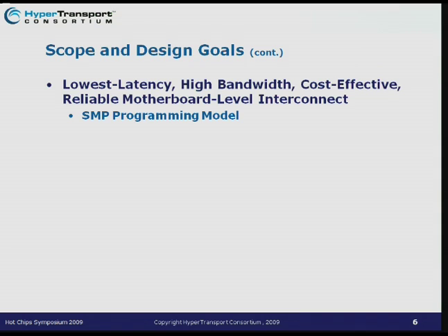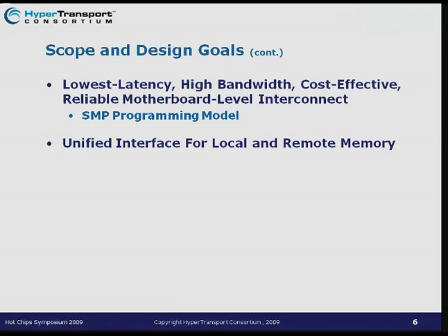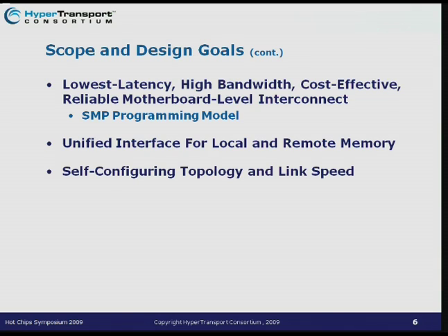And as Chuck mentioned before, the idea was to support the shared memory programming model, so it's an SMP programming model. And as I mentioned before, the idea was to have a unified interface so that processors could access local memory as well as remote memory in exactly the same way. Taking into account that different manufacturers were going to use the processors in different ways, it was necessary to provide support for self-configuring topologies and link speeds so that we could interconnect different devices together, and they could adapt themselves to each other by configuring these things at boot time in an automatic way.